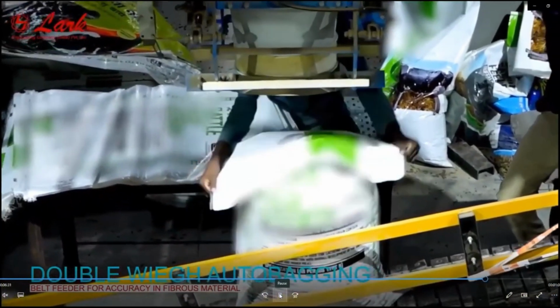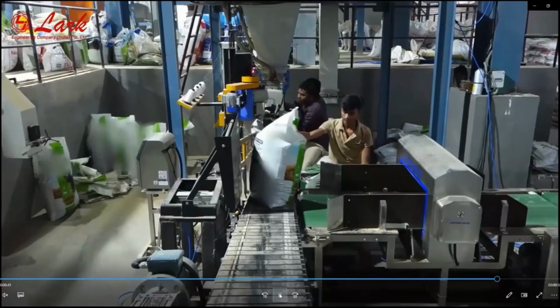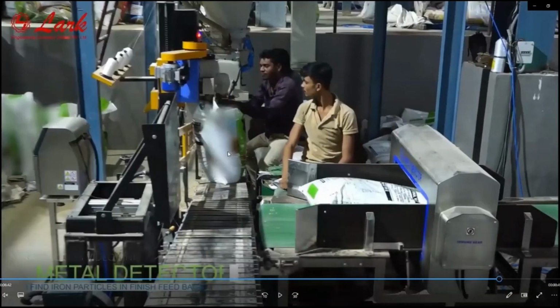And one more new thing we can have in the auto bagging system is the metal detector, because there may be nuts and bolts or some iron particles even after the grinding or pelleting. Someone did maintenance of the pellet elevator and by mistake a spanner or nut bolt was left behind. In poultry it is not an issue, but in cattle this is a big constant, that nut bolt and iron particles in the finished bags.